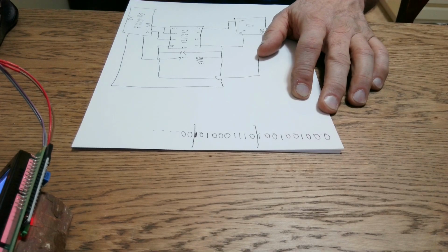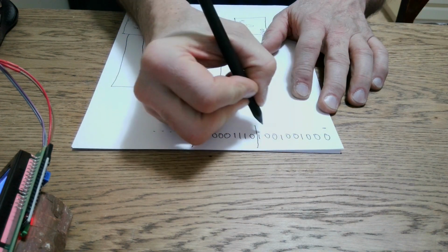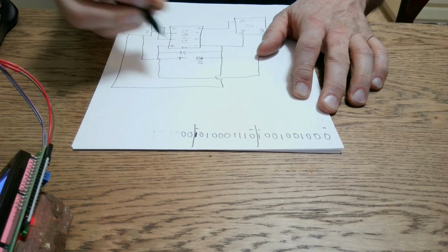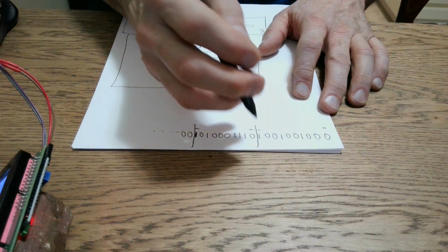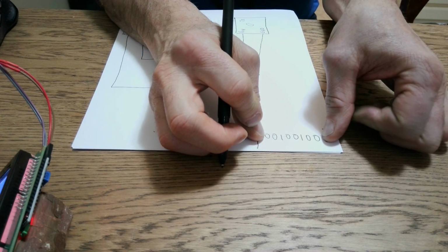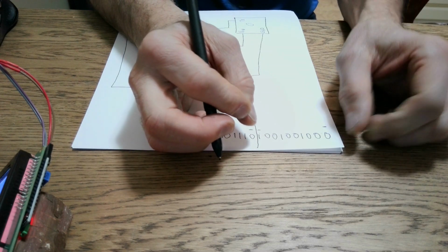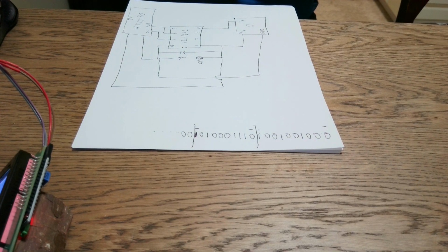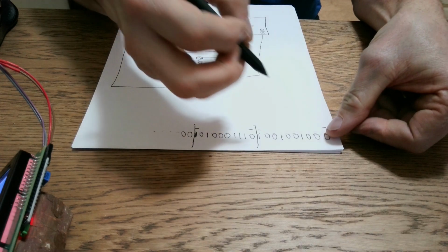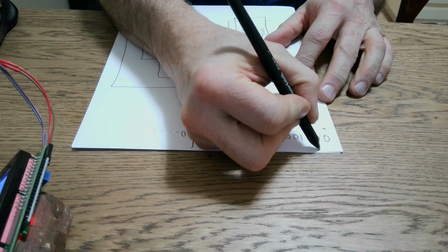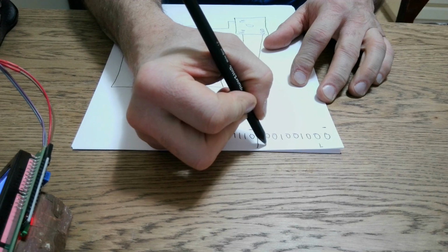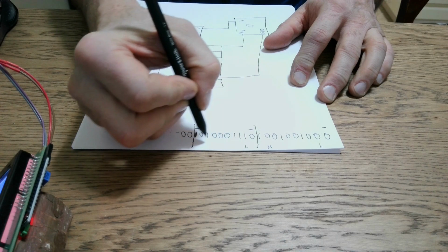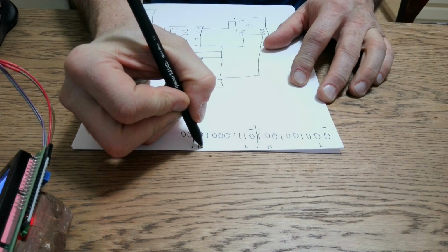So those are obviously not data. They are just merely like parity, if you want to call it that, parity bits. And the data that you want, the 8-bit content, is right in the middle. That is the data we want. So we're going to read that right now. This is actually first in, last out type of data, the way it's read. So this is the least significant bit right there and the most significant bit right here. Same with this one right here. That's the least significant on there and the most significant bit there.